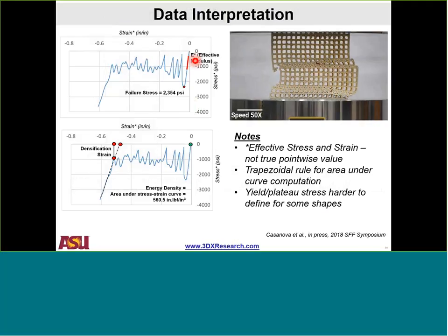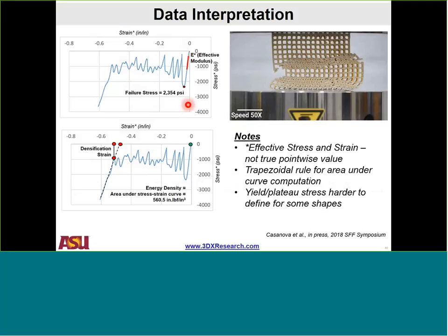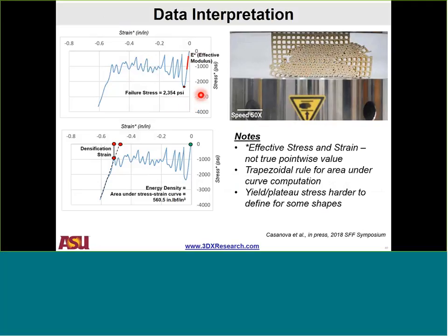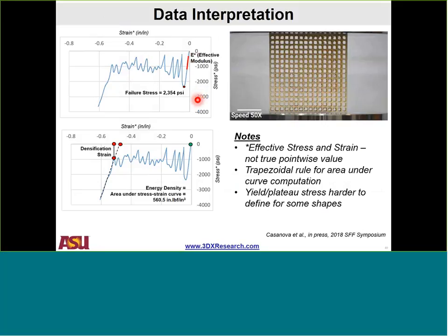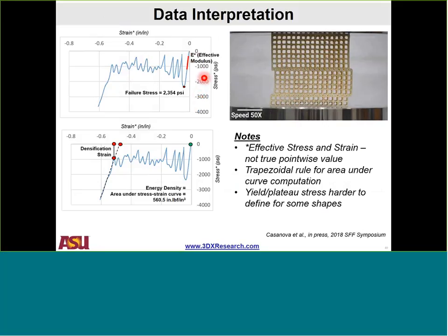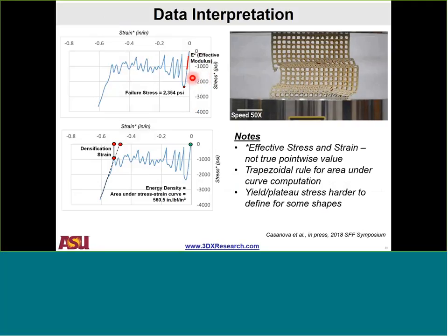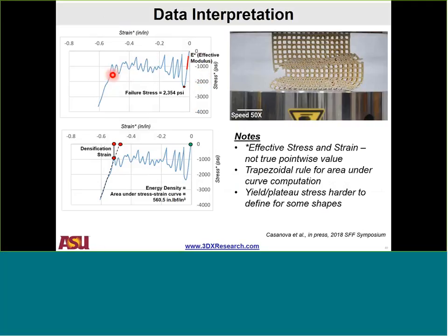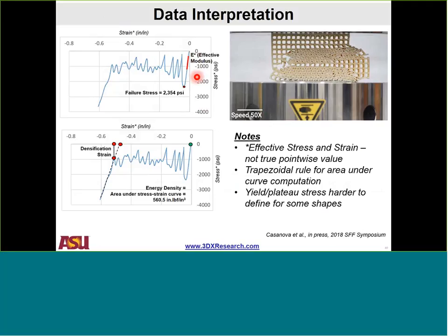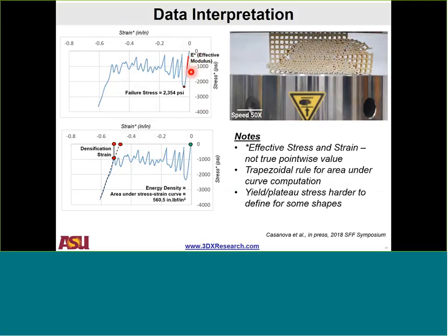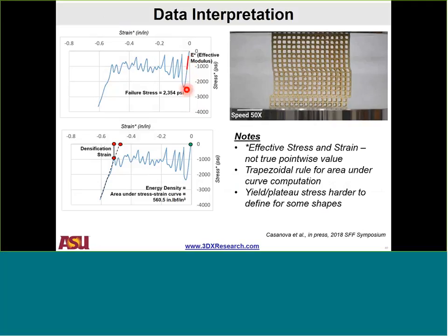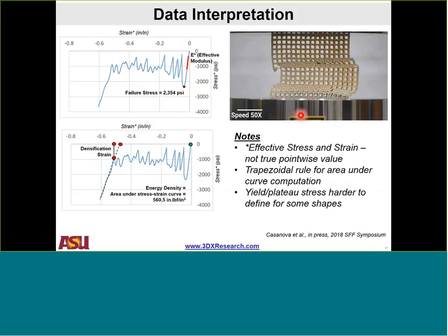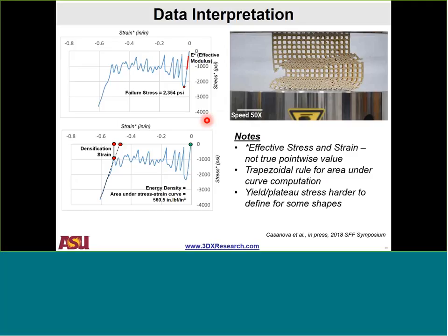This is a typical plot you will get when you conduct a compression test, like this square honeycomb that we have compressed over here. And then people will say, well, what properties can you extract numerically? We don't like curves like this. We want to translate them into some numbers. And we tend to draw these plots like fitting a line that's an effective modulus, estimating maybe the peak stress before the first row of honeycomb cells fails.